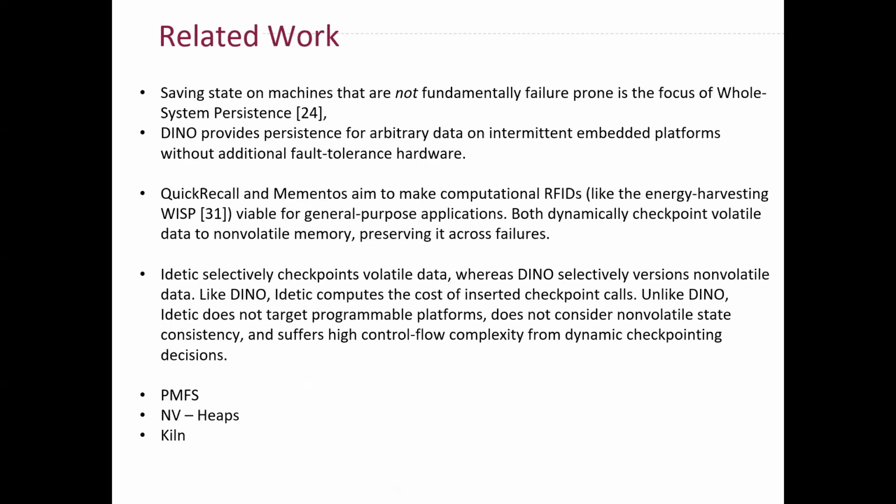The other related works which are similar to DINO are, for example, whole system persistence, which uses a capacitance-backed volatile memory to provide flush-on-failure semantics to an entire operating system. DINO also provides persistence for arbitrary data, but it does so without any additional hardware. We have other papers, Quick Recall and Mementos, which aim to make computational RFIDs viable for general purpose applications. But both use dynamic checkpointing of volatile data to non-volatile memory, preserving it across failures.